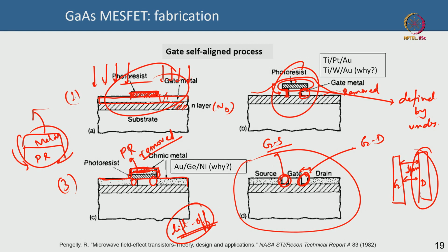The key here is that whenever you form a source drain metal, typically you have to do a high temperature anneal of the source drain metal, so that the contact becomes better. Here it is a channel layer, but you usually have an N plus layer also. By high temperature it can be 600 degrees, 700 degrees, for gallium nitride it could be even 800 or 900 degrees in a field effect transistor. The metal helps improve the contact resistance. The metal could diffuse, metal could spike down, and it will make a better contact with the layer below.